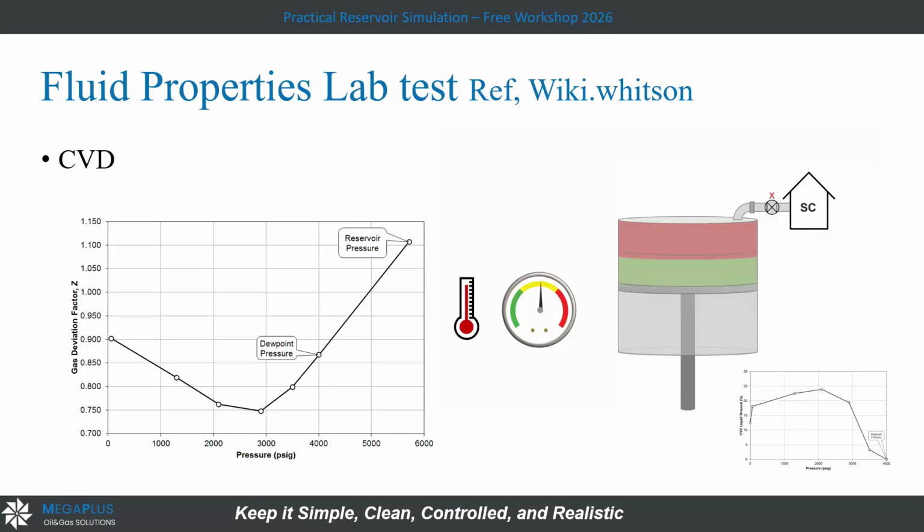So the first dew, or first condensation, will happen. So we have the saturation pressure here, but not a bubble point, it's a dew point. And then after that, we will open, like you will see here. It's like the DLE, but here the gas. We will open, so we got the oil and gas, and analyze at each pressure step. We will analyze this composition.